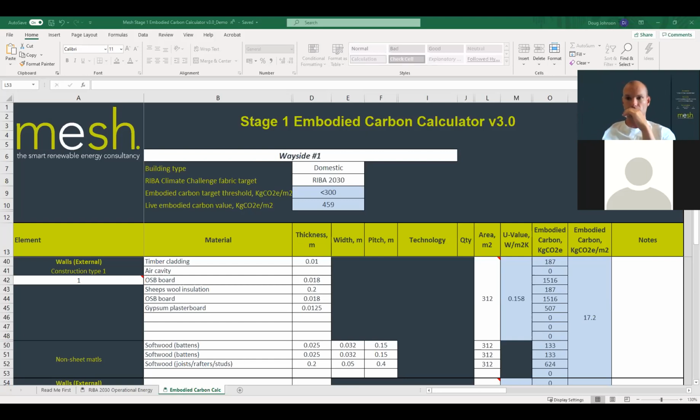Yeah, but the different stages of the EPD, you've got the product stage, which would include the sequestered carbon, and that's the only stage that's included as standard across all the EPDs. So if I was looking at an EPD and I was only looking at stage A1 to A3, then that will include the sequestered carbon. And so if that's the number that one-click LCA are using, that's the number that'll be in your spreadsheet. I mean, these materials take into consideration the whole life, all of those stages. Yeah, but not all EPDs have all of those stages.